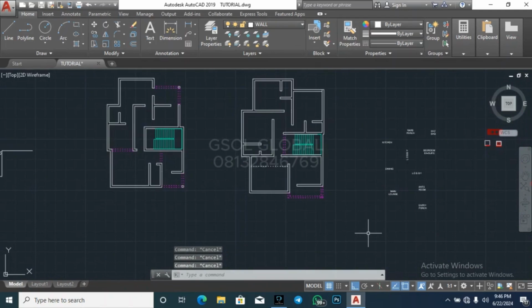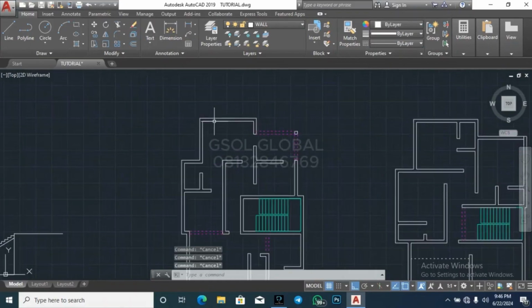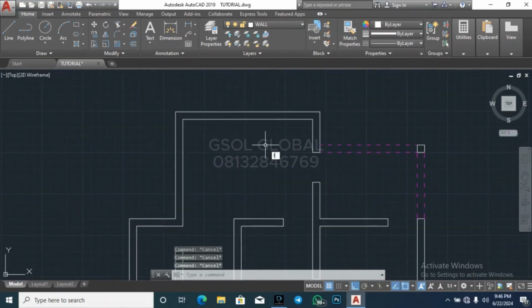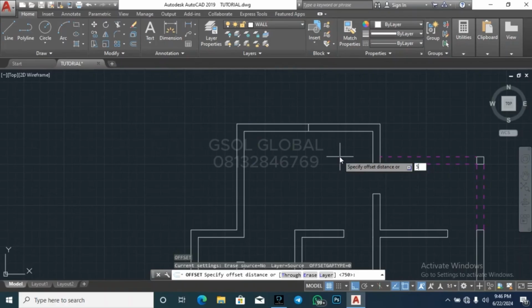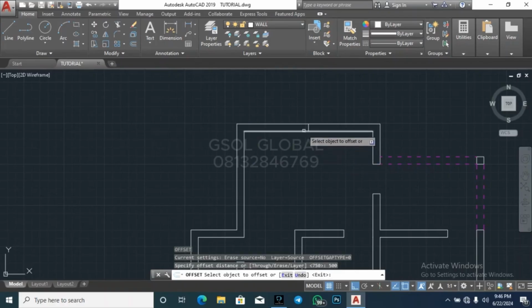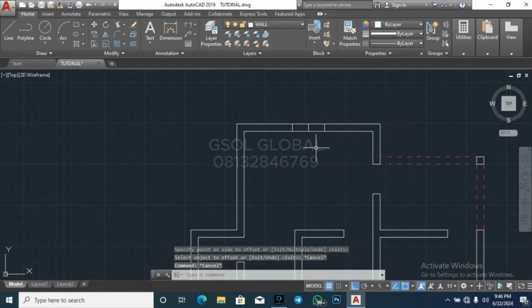So we are done with the doors generally. So let's go ahead and start doing that of the window. For the window, I'm just going to start creating my opening. At this point, we have one here, so I'm going to make an offset of 500. I'm going with the 1 meter window. All right, so 500 here and then 500 here.